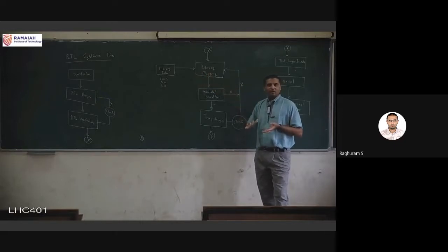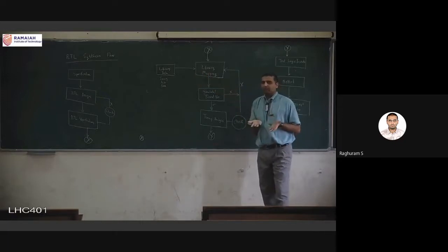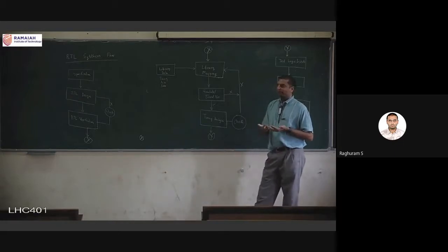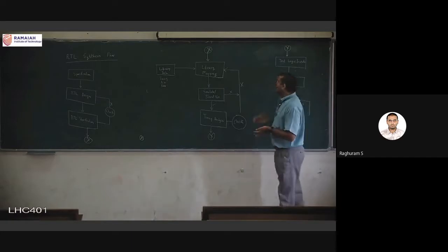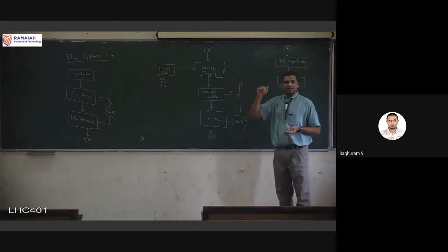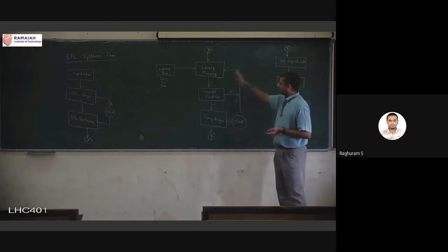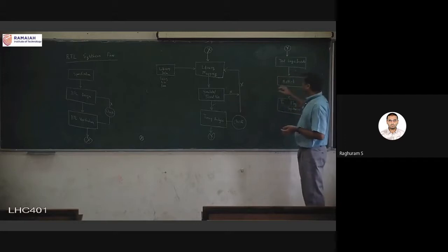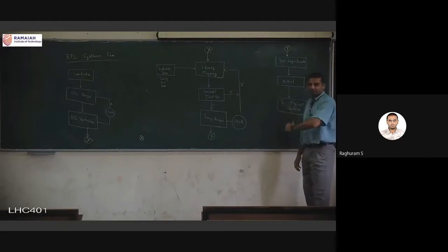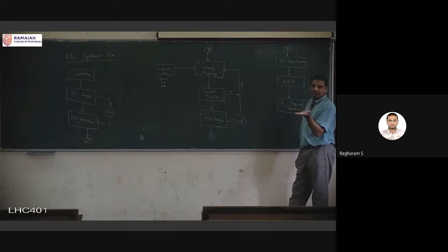They are not going to manufacture it in bulk yet. They have manufactured it, but they are giving you a few prototypes of the manufactured silicon, and this might take a few months before it comes back, but that is called first silicon. In that first silicon, the test logic is already inserted. We are not inserting it now. During the design phase itself, we have this netlist. This is going for physical synthesis. Back-end design happens, tape out happens, and it comes back to me. That is the first actual silicon implementation of my design.